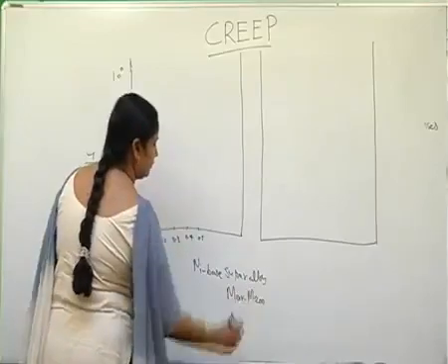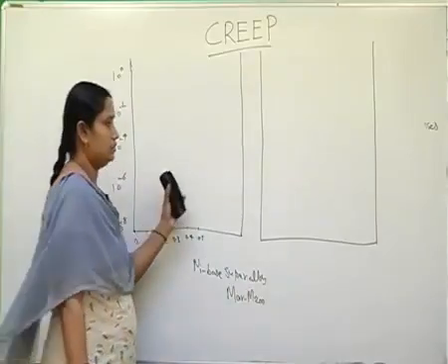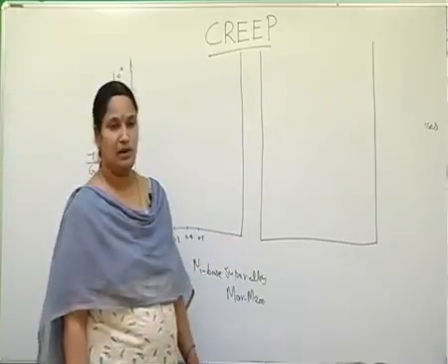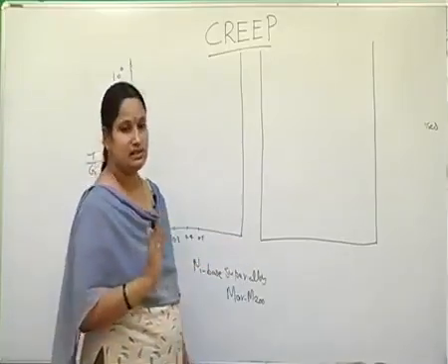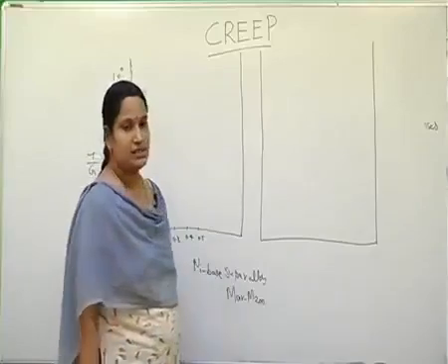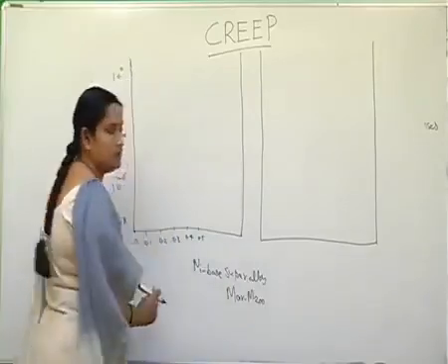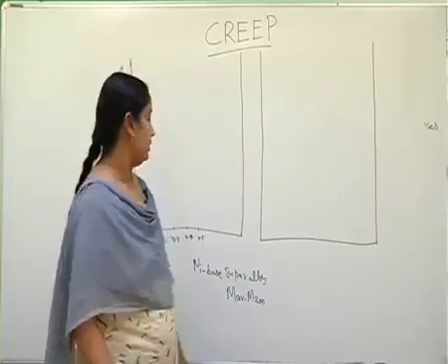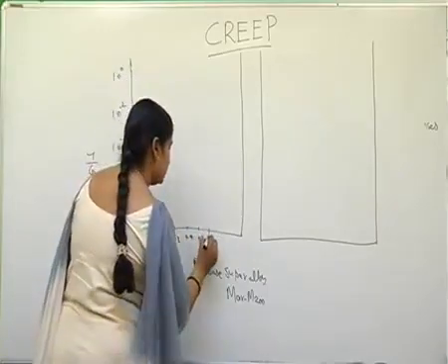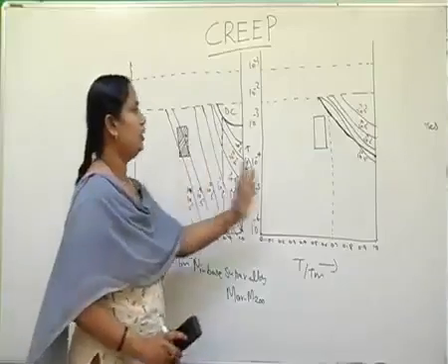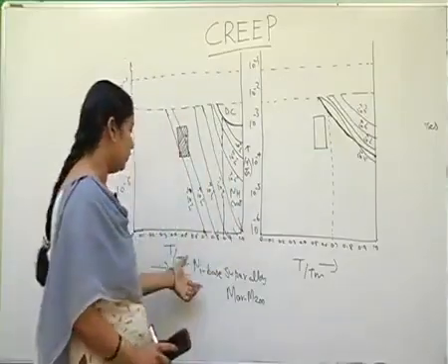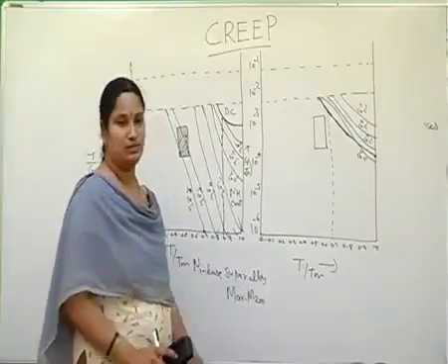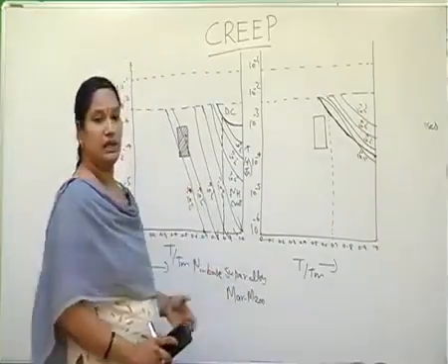So these are the two deformation mechanism maps for this nickel base superalloy for different grain sizes: for grain size of 1 centimeter and for grain size of 100 micrometers. These are the two maps for MAR M200, which is used as a turbine blade.